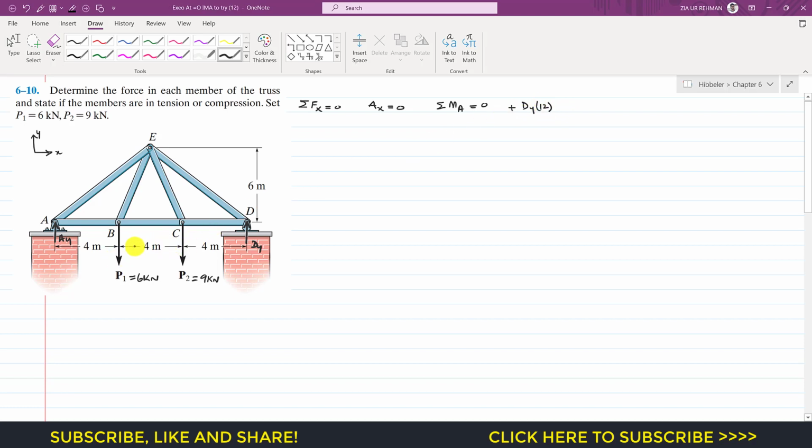Then this P1 and P2, both of these are producing the clockwise moment. So the moment produced by P1 is clockwise, so you have to put minus sign. P1 is 6 kilonewton and the moment arm is 4. The perpendicular distance of this P1 from that point A is 4 meters. Similarly, minus 9 for P2, and the perpendicular distance of P2 from that point A is 8 meters, and this is equal to 0.